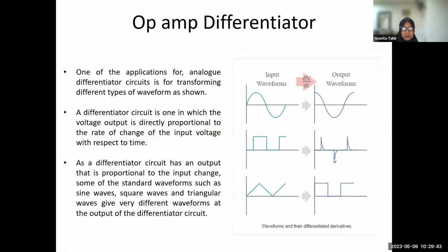Okay, so we are going to look at another tool, which is op-amp as a differentiator. It's not differential. Differential is the difference between two inputs. It's like a subtractor. This is a differentiator. The mathematical operation of a differentiator, d/dt. After this, we're going to see op-amp as an integrator.